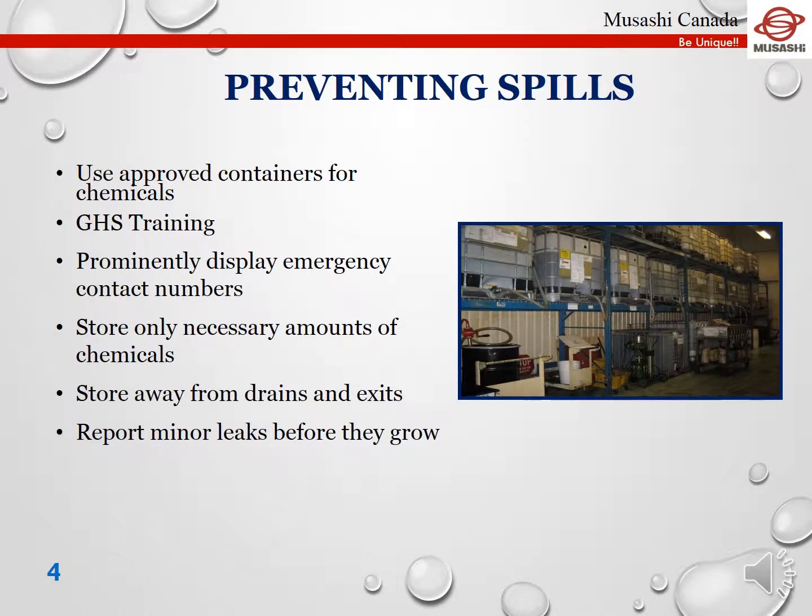Preventing spills. Use approved containers for chemicals. GHS training. Prominently display emergency contact numbers. Store only necessary amounts of chemicals. Store away from drains and exits. Report minor leaks before they grow.